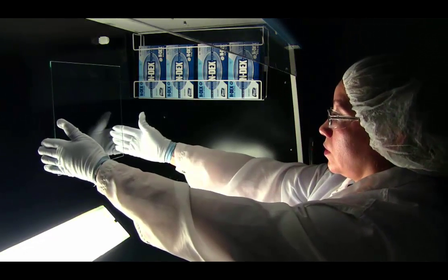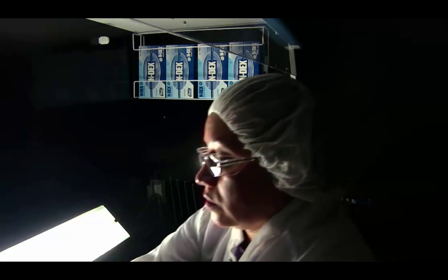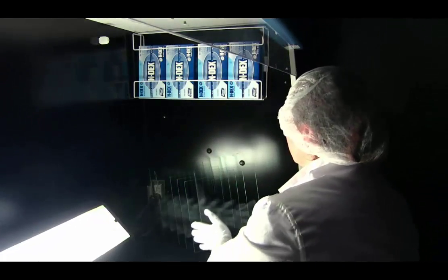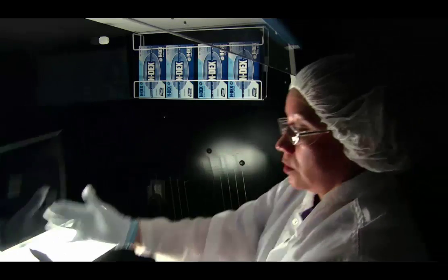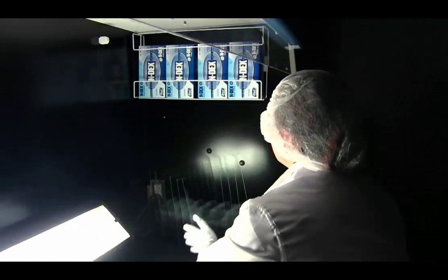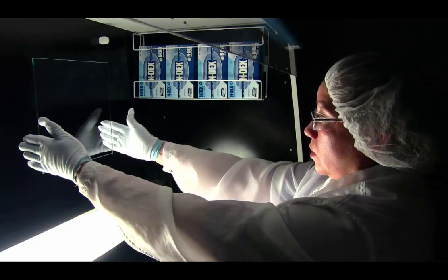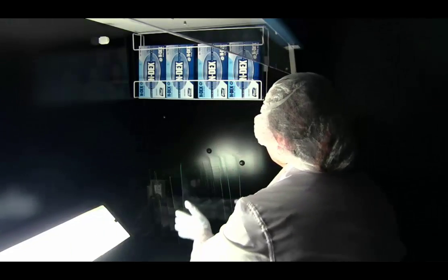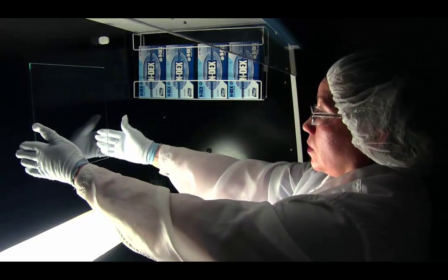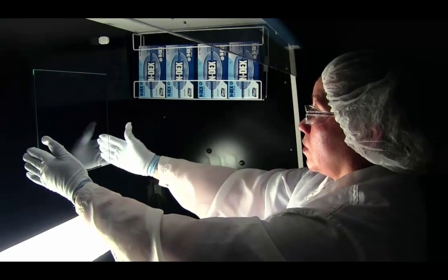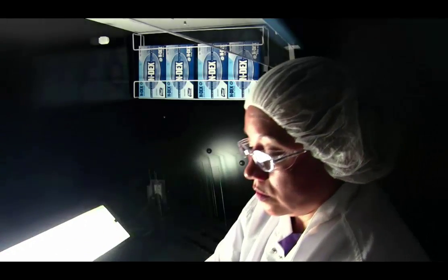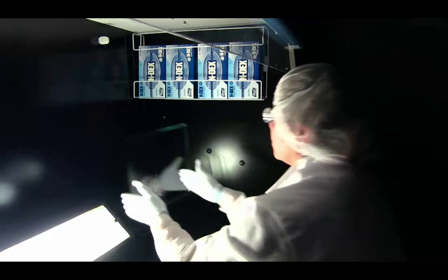The backlight is angled at 45 degrees, allowing the user, in this case our inspector, to view the parts in transmission. You can see the inspectors handling the edges of the glass to protect the front and rear surfaces from contamination from the hands, using clean barrier gloves during the handling and inspect process. Parts are viewed looking through the glass using the flat black background for a period of 2 to 7 seconds. The inspector scans the glass from side to side, top to bottom, looking for chips, digs, scratches, and other common defects associated with the glass manufacturing process.